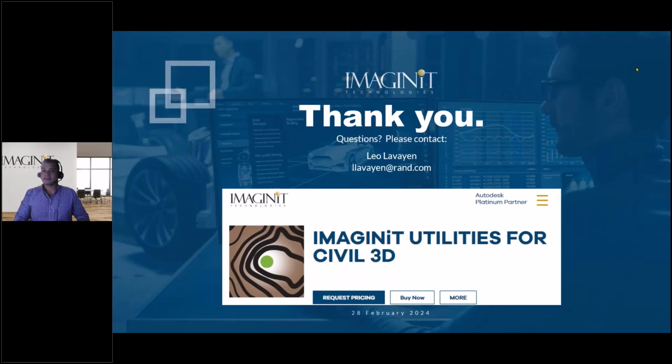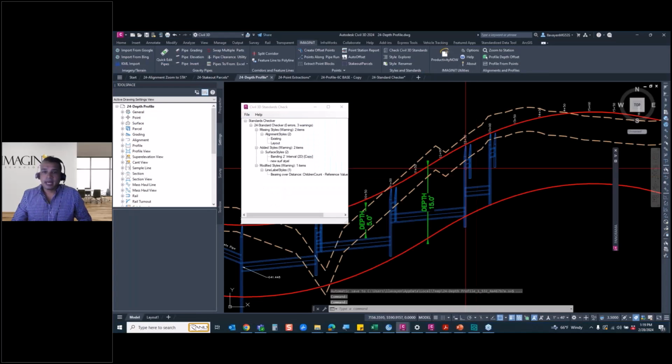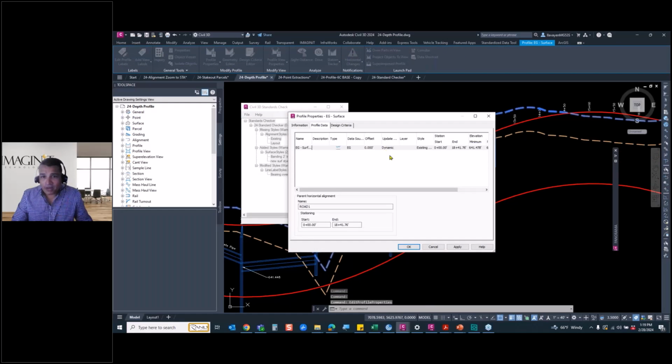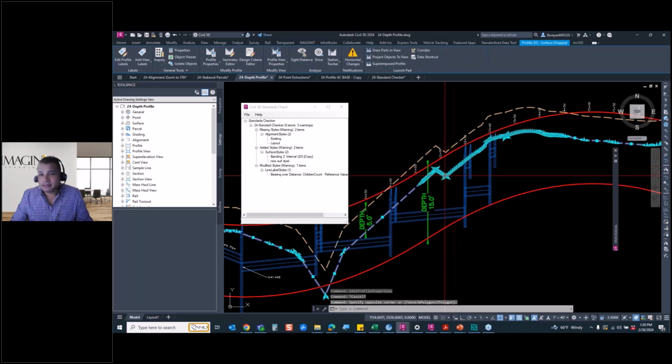The first one says, if you use the drop profile on a surface profile, if the surface changes, does the profile update, or is the drop profile static? Great question. So over here, when we start looking at it, this is the original surface. And what you'll notice is that this profile is dynamically tied to the terrain. So if the terrain changes, that profile would update. Notice over here that the copy of it has about a gazillion vertices. Visually, it's even different.